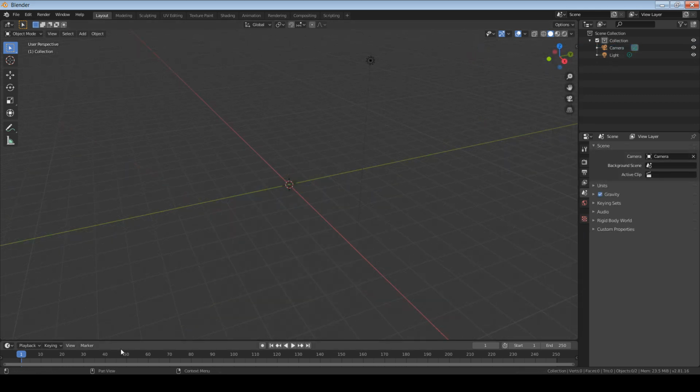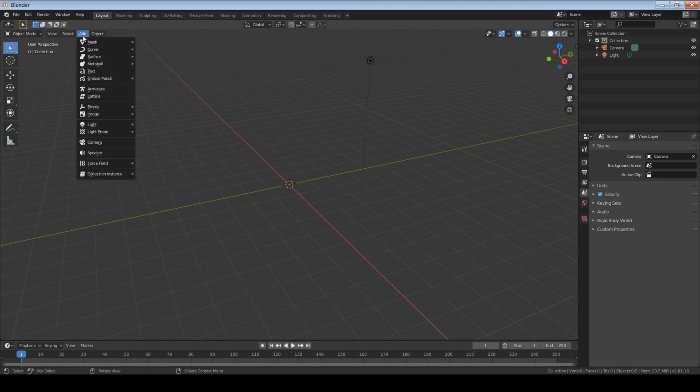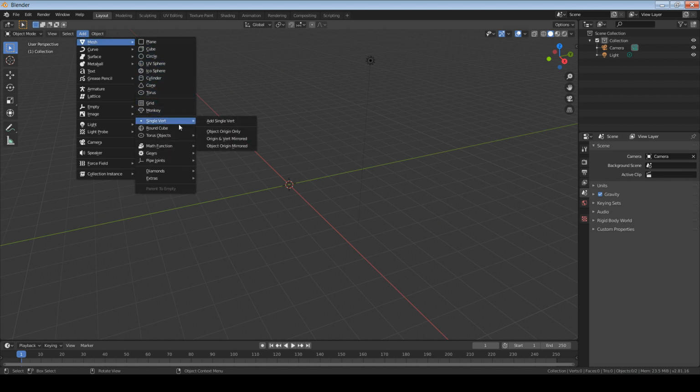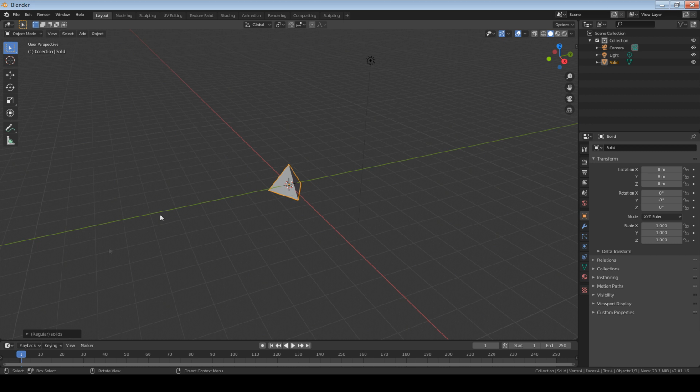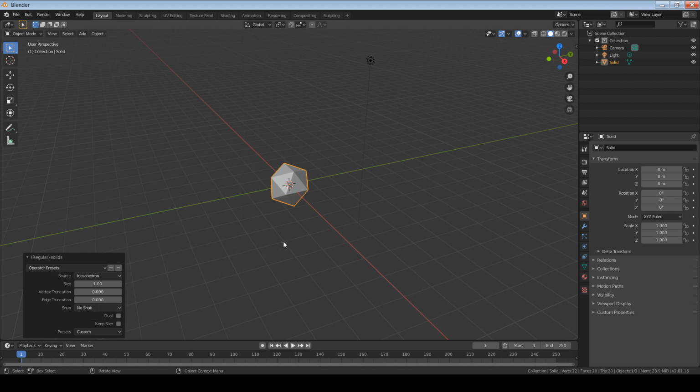Now that we've finally reached the D20 stage, you should probably brace yourself because there will be a lot of angles thrown at you thanks to the number of sides. With that warning out of the way, go ahead and delete the default cube that Blender loves to give you, and then go to Add, Mesh, Mathematical Functions, Regular Solids, click the dialog box in the bottom left-hand corner of the work area, and select icosahedron from the drop-down menu.